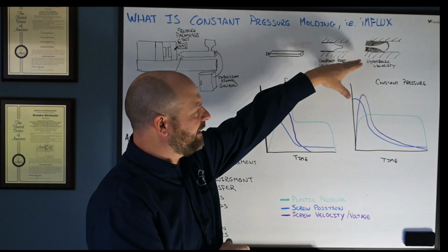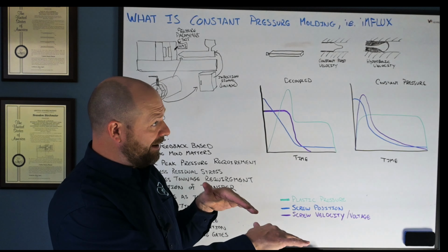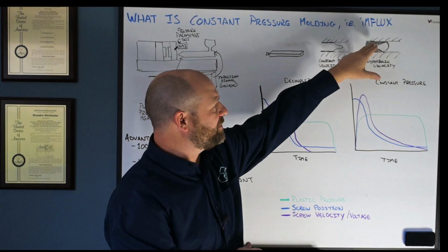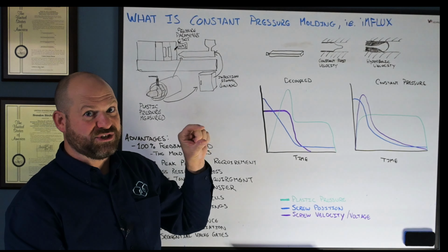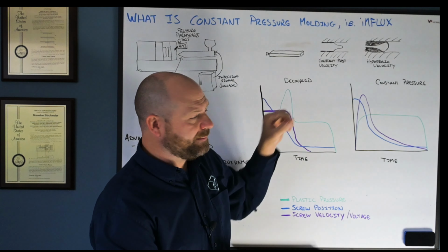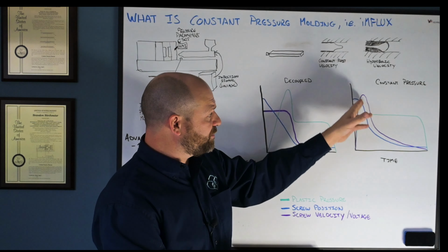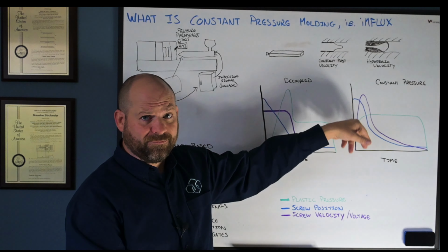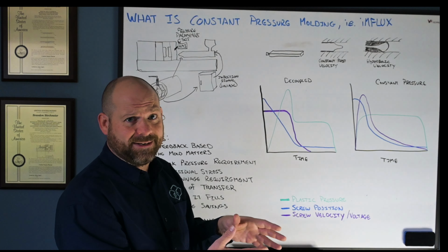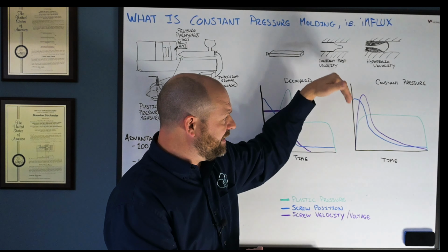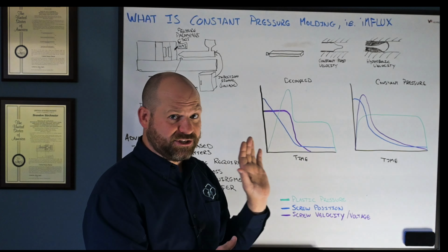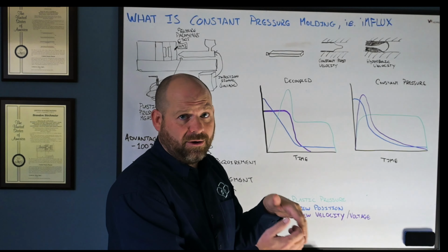And if you were to, again, look at the flow front as it's traveling through the tool, what's happening is there's a much thicker skin layer in this instance, and a much smaller channel of molten material going through. Because we're decelerating, we create a lot of shear up front to get the polymer moving and aligned, but then there's a deceleration, so the flow front continues to move forward, but it's also packing that part out as it's moving forward.